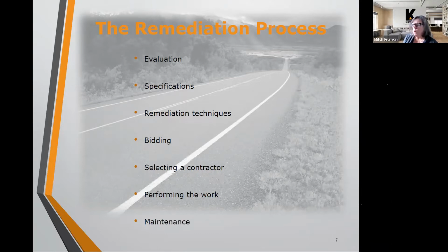So when we get the bids back and we analyze the bids, one of the things we do is we add a line item. Kipcon adds in, not the contractor, a line item increase of between 10 and 20%. So we'll show you what a 10% increase on the project would be and a 20% increase on the project would be, and that contingency amount is typical, we find, across the board for pavement projects. Pavement projects usually come in with extras somewhere around 15% above base bid.